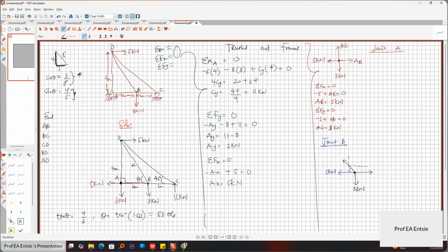So now let's do the force analysis, right? Let's do the force analysis. So what will I do? I will find the summation of forces in the x. So it will be minus 5. So this one, if we should resolve it, we get what's the force there? Remember there is BD. So we get BD cos theta, then here will be BD sin theta. We know this already. So minus 5 going to the left plus what?